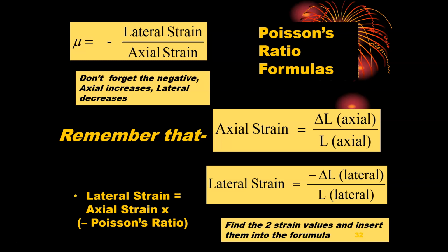So the lateral deformation in Z is the lateral strain times the original length. So the lateral deformation equals negative 0.007 again, and just times the 500 thousandths. And the lateral deformation is negative 0.0035.